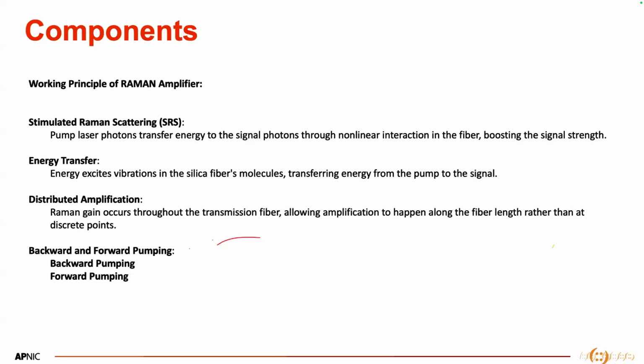When we are using forward pumping, we are basically offering higher gain efficiency. But when we are doing backward pumping, we are basically offering better noise performance for the signal. So that is what Raman amplifier is all about.